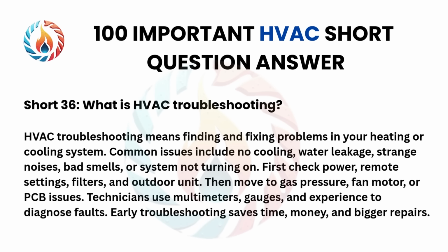First check power, remote settings, filters, and outdoor unit. Then move to gas pressure, fan motor, or PCB issues. Technicians use multimeters, gauges, and experience to diagnose faults. Early troubleshooting saves time, money, and bigger repairs.